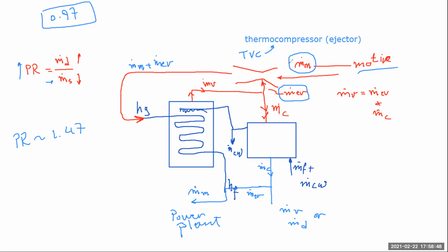Or in power plants and thermal desalination plants, you'll find that ejectors are used a lot, not only as a thermo vapor compressor, but sometimes because of the vacuum effect that it has. So sometimes we connect it to the units to get rid of the non-condensable gases. We have a flow coming here, and the flow will go here. It creates suction in this area. It takes out the carbon dioxide and all the non-condensable gases, and you do venting for your units this way. So they have very good applications.